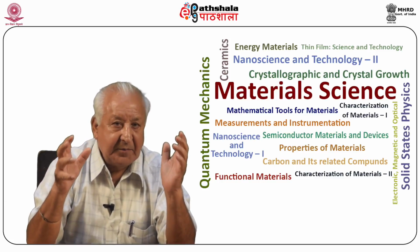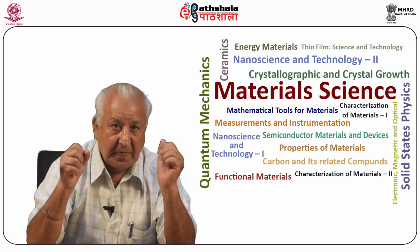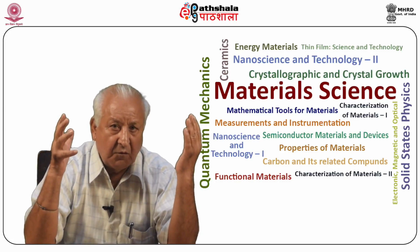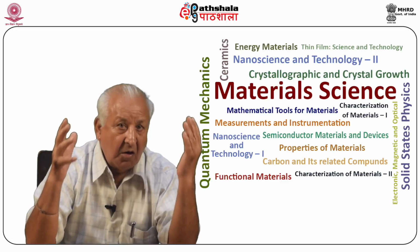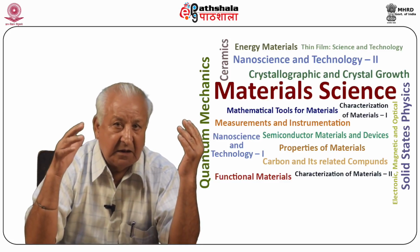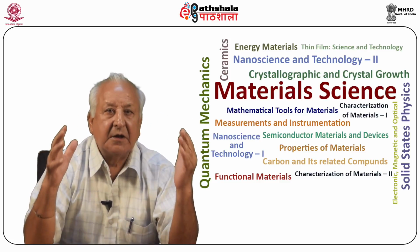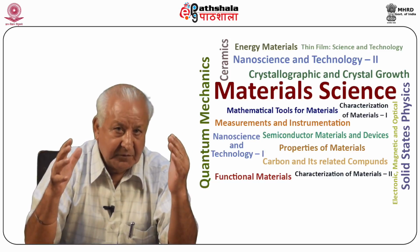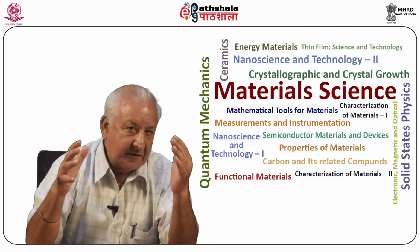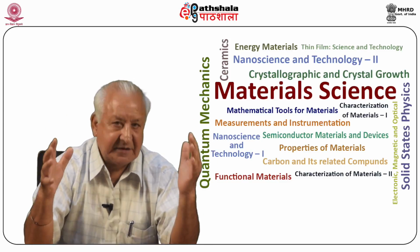SEM and EPMA use this emission for analysis. It may also happen that a photon of ultraviolet or of visible light may be emitted either in place of X-ray photon or in combination with the X-ray photon. This phenomenon is known as cathodoluminescence, which is also used in image formation by the SEM.